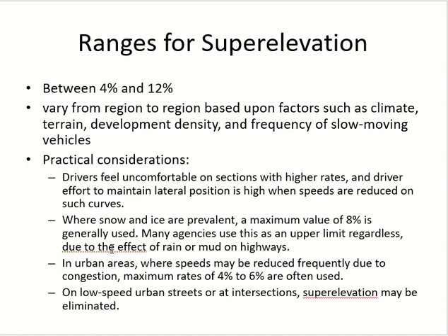The value of superelevation depends upon these things: the climate. Something which I mentioned in the last topic as well. If your climate is such that you will frequently have a wet surface, then the superelevation should be less, because on a wet surface there is a chance of sliding.